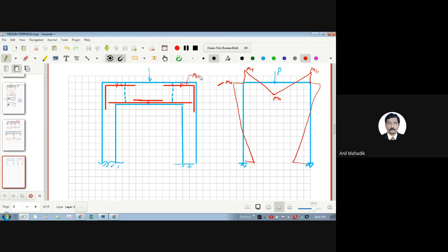So M_h in beam, and this will be M_h in column, but they are same, or we can say continuous bars. So this is a detailing for this. So this is the main steel. Now there will be main steel over here also, don't forget. यहाँ भी रहेगा ना, यहाँ भी है ना tension, ये वाला अंदर की side में, and there is a tension here also in this side.